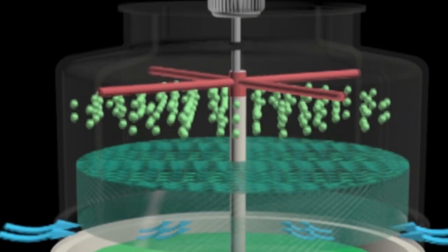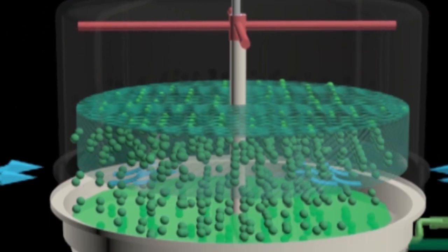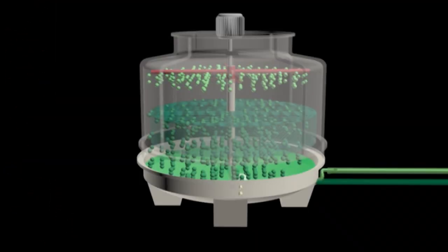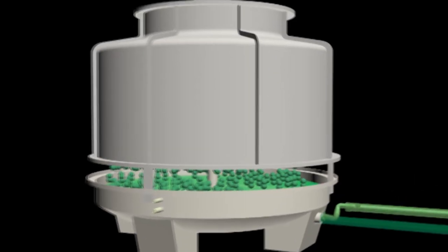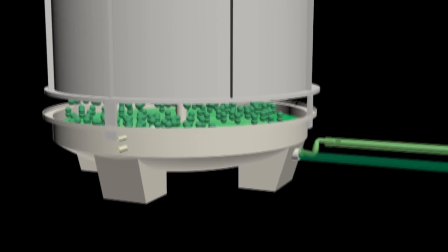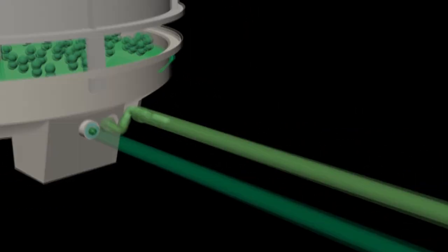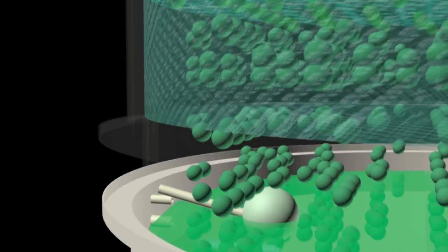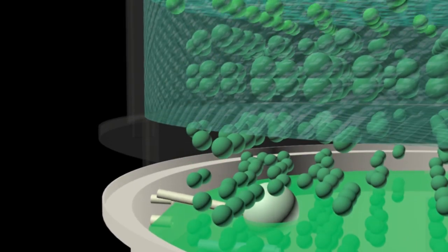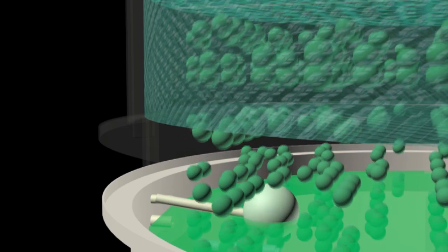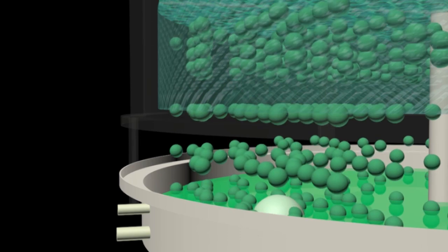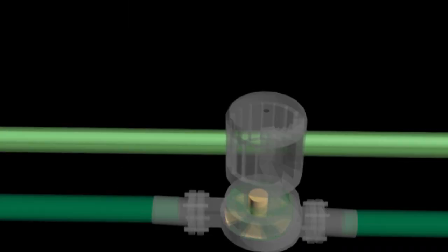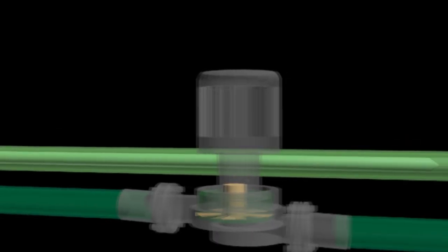Condenser water which has eliminated its heat to the surrounding air will accumulate in the basin under the cooling tower. Condenser water that flows out from the cooling tower to the chiller is called condenser water supply. This condenser water will flow back to the chiller to continue heat absorbing work from the refrigerant. The buoy system at the water basin is connected to the make-up water tank. It works for adding water when the water level in the basin decreases to a certain level due to evaporation. This condenser water cycle will continuously flow as long as the centrifugal pump is in good working condition.